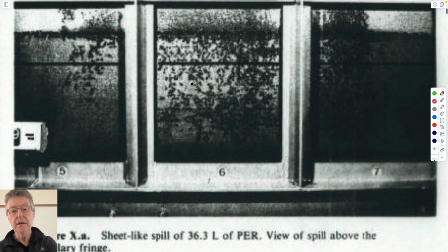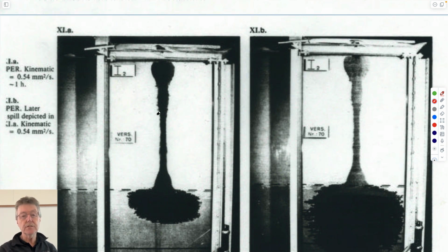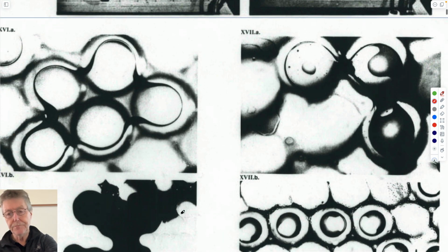See how it behaves in the vadose zone, spill it in the vadose zone, and then see what it does when it hits the water table. All these nice visualizations. And then look at the individual grains of the pores within the aquifer. So these would be pores, and these would be the individual grains, and it would be filled with water, but the colored fluids are actually the immiscible parts, which exist separately as separate fluids.